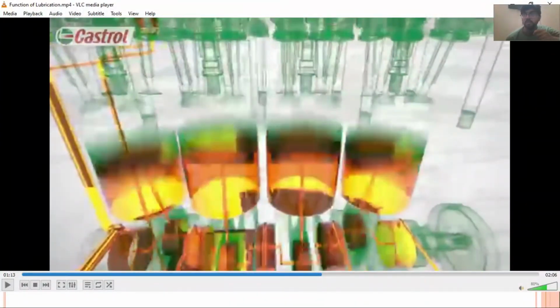Okay, one very important factor which is mentioned here, that oil basically experiences the highest mechanical stresses where we have the valve train, and your oil should have that much film strength, that much oiliness, so that it can bear all the mechanical stresses which are occurring in the valve train.